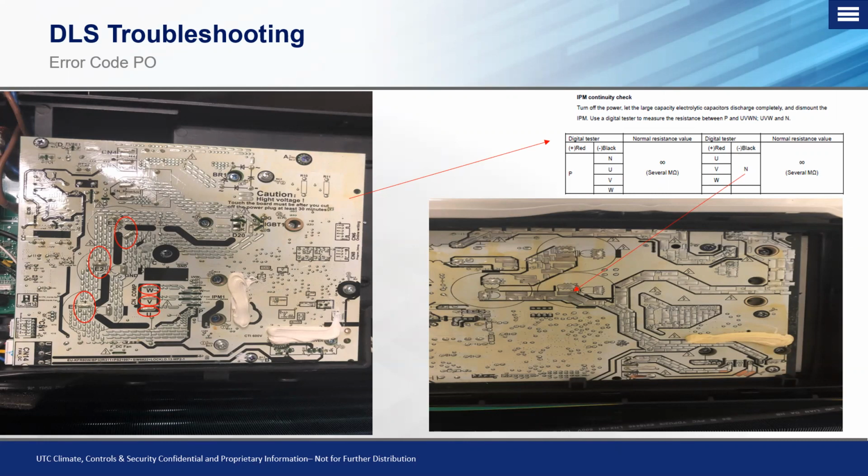This is typically on our smaller single zone units, such as the 9, 12, and 18, where we have a single board, where it's a main PC board and an inverter drive in one. And you can always tell that because, one, there's only one board, and two, there's a heat sink connected to that board. That heat sink is essentially a way for those IGBTs or those pulsating switches to reject their heat so that board does not overheat. That's oftentimes why you'll see these boards face down and in the condensing section. So when that fan motor is running, it's passing air through the fins of that heat sink itself, so they can get rid of that heat.